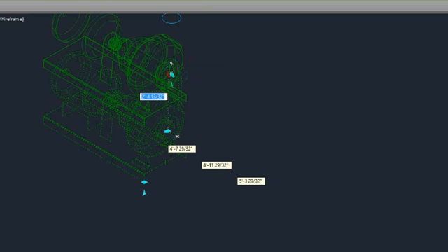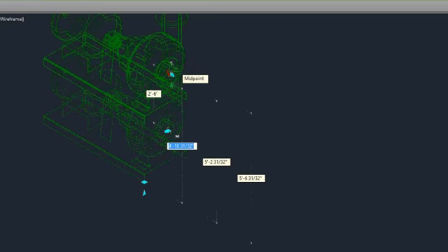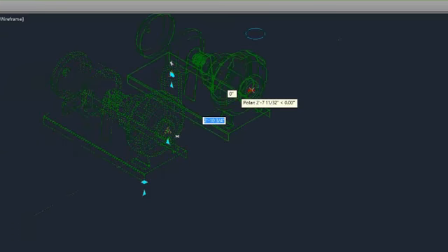How far do I want to move it from its current location, which is exactly the same as the relative move from the base point of the equipment. And finally I hit tab once more, and whatever elevation I put in there will become my bottom of pipe elevation for that connector. Then again, you have another move point that you can choose to move from that connector, and you can move anywhere you want.